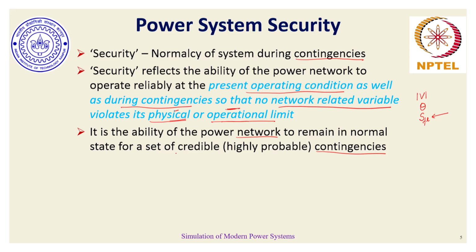So in order to have a balance between the investment involved in setting up the system which would control and maintain the network during contingency and the number of contingencies that can occur in the network, based on operators' experience, operators generally plan security functions for credible contingencies which have higher probability, the probability being more than a particular threshold based on the operator's confidence.